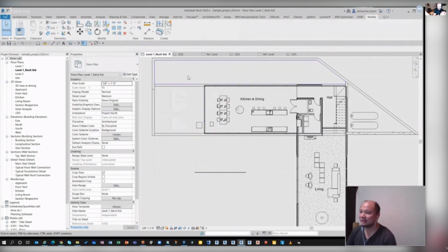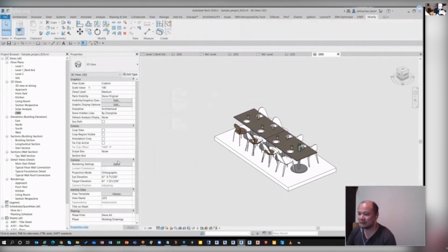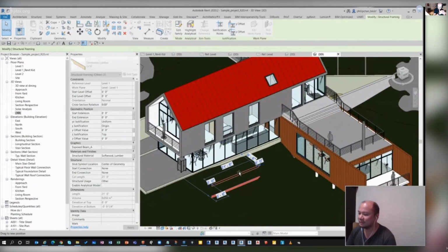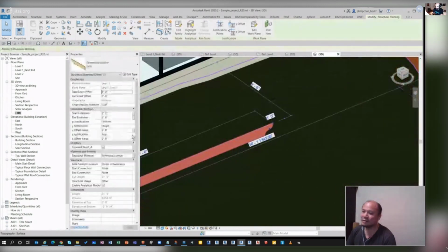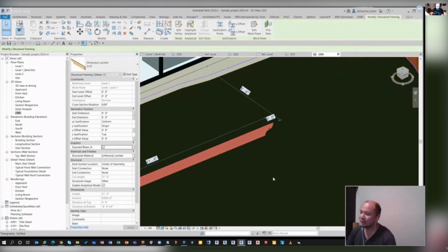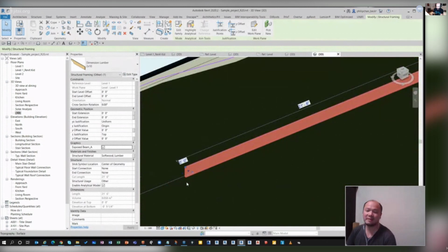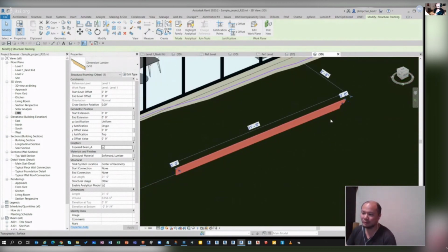So let's take a look in 3D together. Of course, I did that earlier. Okay, so look at that right now. So I have this beam family here. What happens is, because it's an instance parameter, now I have this checkbox here that I could turn on or off any way I like it. Of course, if I make the same thing on the other end and have another yes/no parameter associated with that profile, I can now independently control my exposed beam wherever I want it.